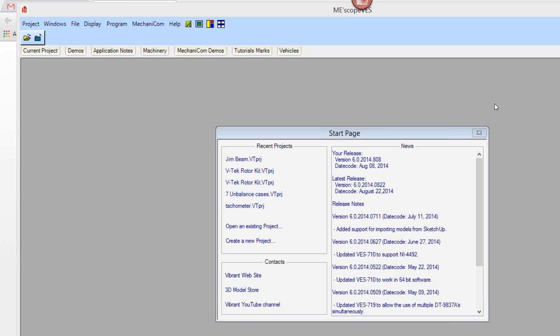Whatever is in our response, we're going to see some peaks in that data, but we're also going to have the phase of that roving response relative to the reference. Now, if we collect a whole set of data like that, then what we've got is the phase of each of the roving responses relative to each other. Since they're all relative to the reference, they're also relative to each other.